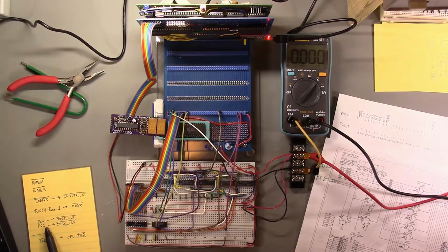The PC0 and PC1 signals from the 82C55A are being used to drive the IRQ3 clear and IRQ6 clear inputs to essentially allow us to reset the flip-flops that do the edge detection. And finally, the IRQ out output from the interrupt controller has been connected to the CPU's IRQ input.